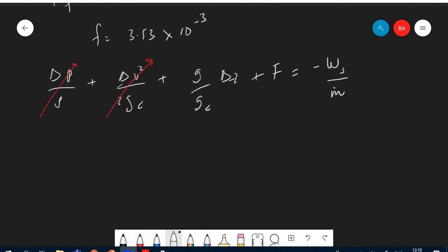So just substituting, this is 9.8, which is the G term, over 1 for SI units, into 5.06 plus F. F is the friction factor term, which is 2FL U square over GC D, because you're substituting the KF term as well.